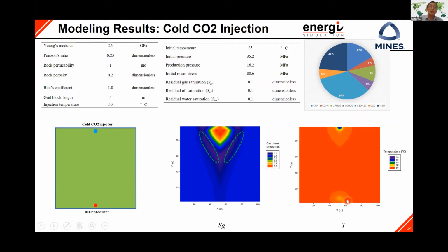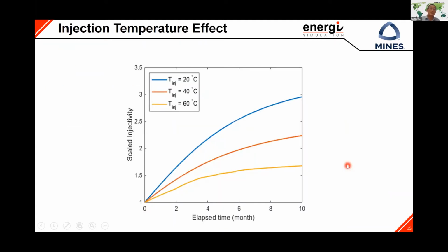The reason we include the temperature impact is that in CO2 flooding, CO2 phase behavior is different from most other gases, right? It's changing from gas phase, supercritical, to liquid phase all the time in reservoir conditions. We know the Joule-Thomson effect, right? It's associated with thermal exchange. So even when you inject, you hope it's an isothermal system. It's not. So you will see the impact on injectivity.